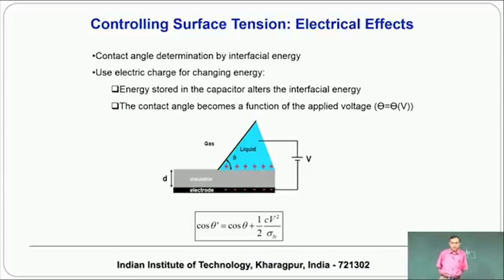and typically the insulator is designed with a purpose. The insulator itself can be some PDMS, for example. The purpose of the insulator is to act as a capacitor and store some charge, and then you can have a part of the insulator as a very thin hydrophobic coating, which may be for example Teflon.